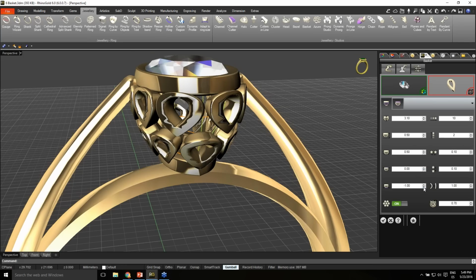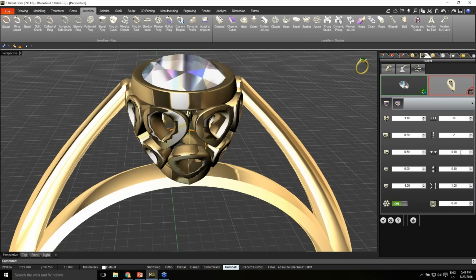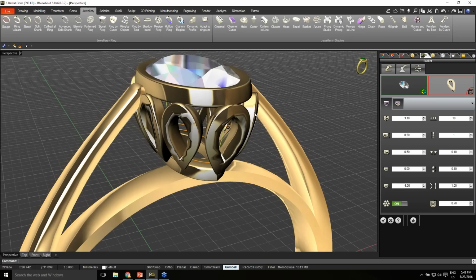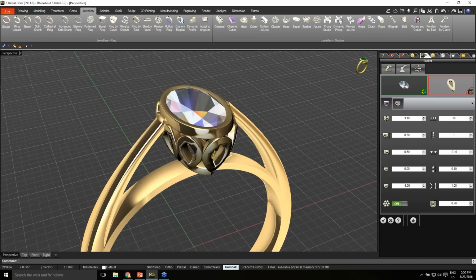And of course there are also the bottom rail, so we can adjust the basket as we want. There will be many more possibilities. So for instance, in here I'm going to go back to a single pattern. I can adjust all the options, the space between them, the number of copies. All these are available. And for instance, if I want to adjust them to touch each other, I'm going just to the distance between them, and I will make sure that in this case it is a negative distance. So we will be able to customize the basket as we want.